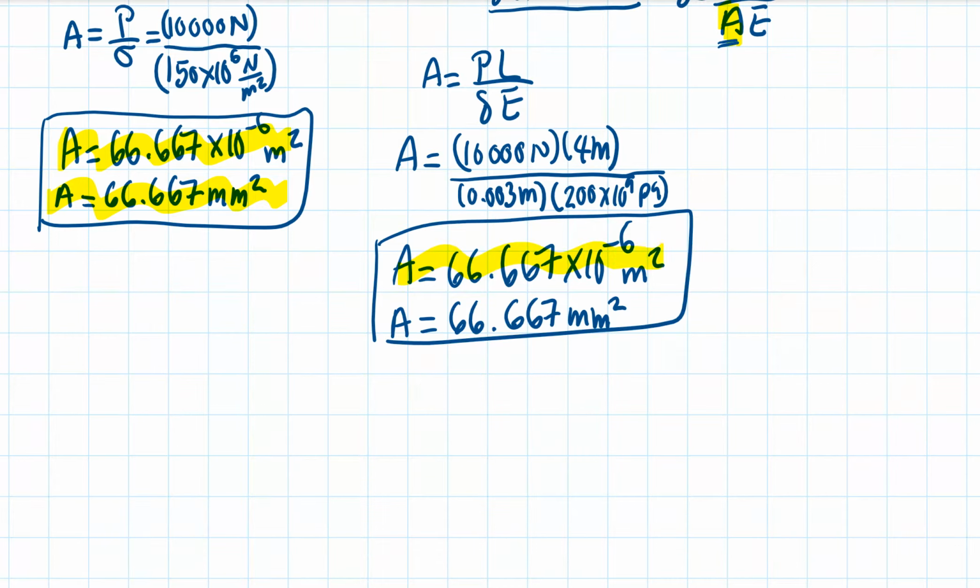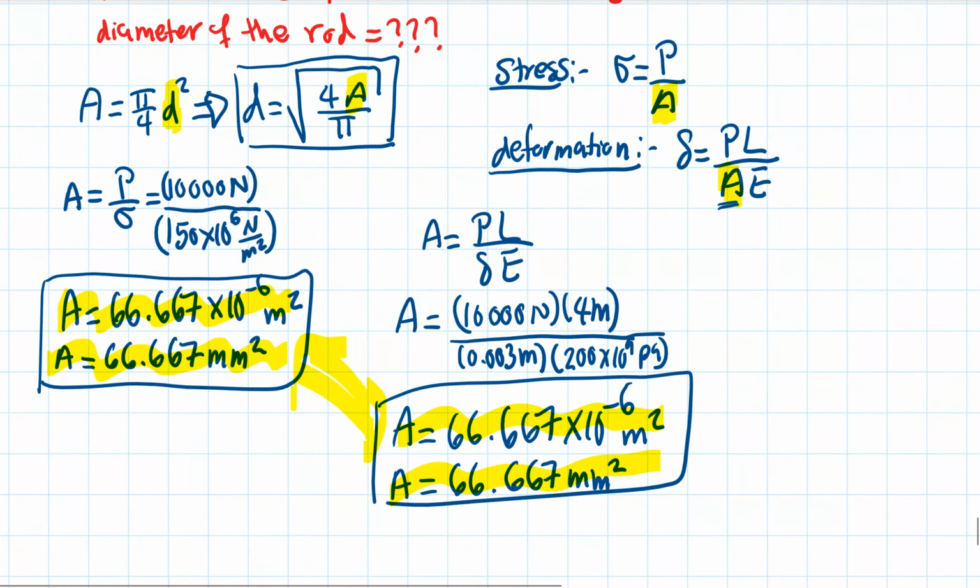So in here we have these two areas. Which area are we going to use? They are the same. And again, if they were different, then the larger area would govern. So we will take this area and plug it into our diameter equation.